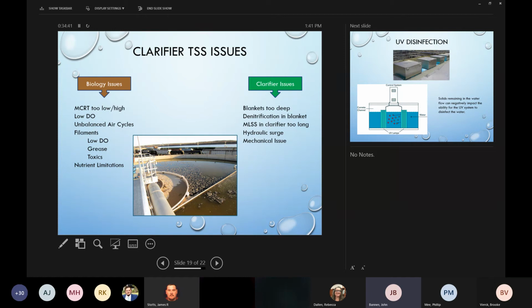We have biological issues that can be actually causing the sludge to rise. And then there could be physical issues with the clarifier or the operations of the clarifier that are creating these conditions. This is a danger for us in treatment, because the treated water of a clarifier is what is at the very top of the clarifier that goes over the weir that is on the outside of that circle. That is where the treated water leaves this tank. That is supposed to be the clear and clean water. And so these can become problems.